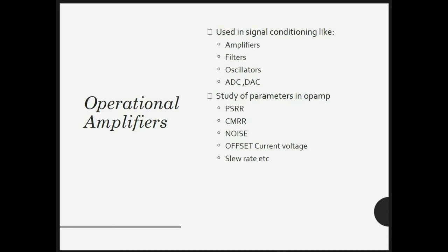The popularity of operational amplifiers as a building block in analog circuits is due to their versatility. Due to negative feedback, the characteristics of an operational amplifier circuit, its gain, input and output impedance, bandwidth, etc. are determined by external components and have little dependence on temperature coefficients or manufacturing variations in the op-amp itself.